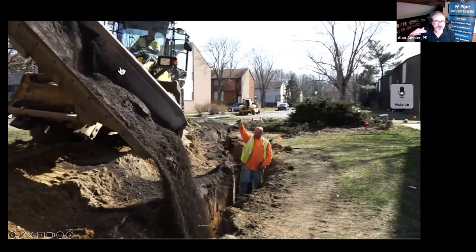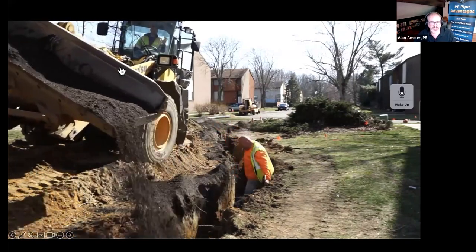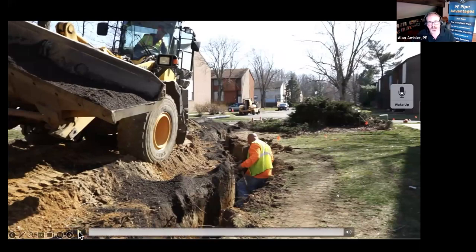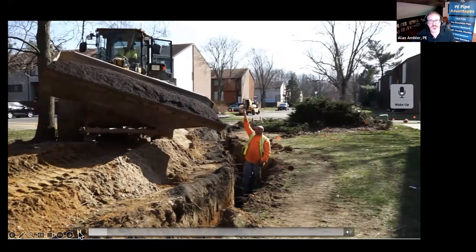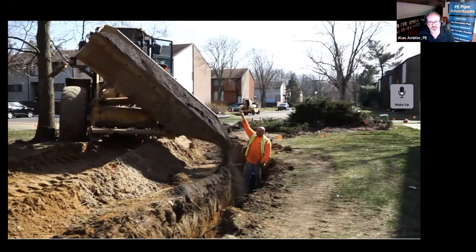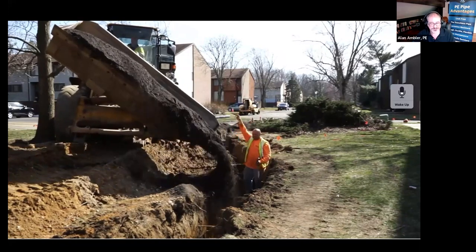So we're going to look at 1-foot lifts that you would be able to backfill back on top of the pipe. The reason why we limit it to that is because the compactor can only get so far through that, and we want to make sure that we have appropriate density through it. So here, it's a pretty simple operation. They started to excavate, laid down proper bedding for the pipe, then bring back that embedment around the pipe and start to backfill it. So it's pretty effective for the 2 employees you're seeing here.